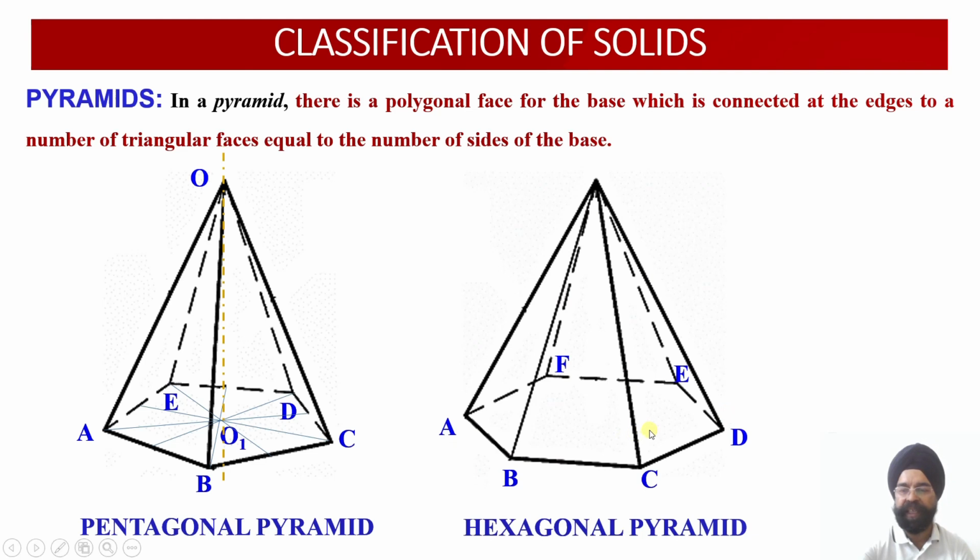Then you have the hexagon. So once again, the naming will be A, B, C, D, E, F. Now to work out the center point, join the diagonal AD, join the diagonal BE and join the diagonal CF. Once you join all these diagonals, you get the center point or the axis point. Through this axis point, draw the vertical axis representation, small, big, small, big, small, big. So this is going to be your axis line. So this will provide you the axis.